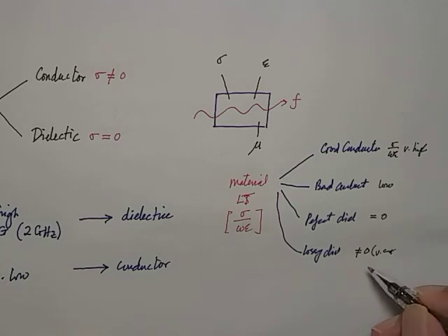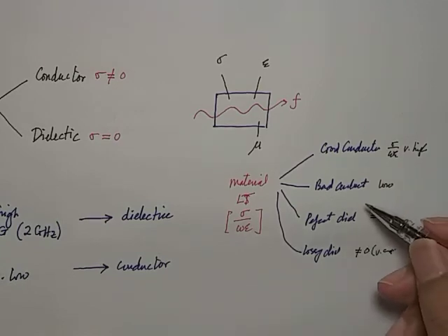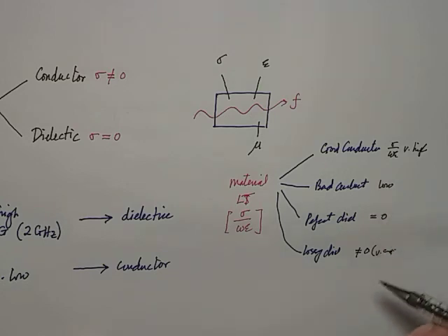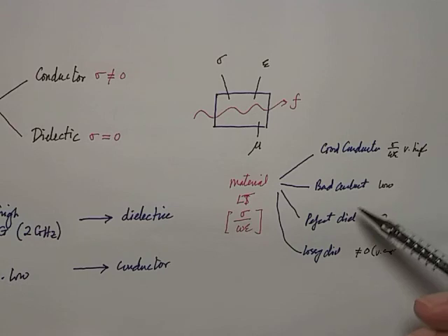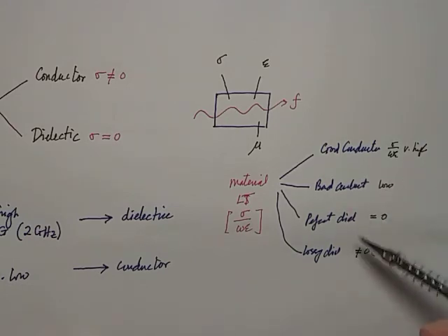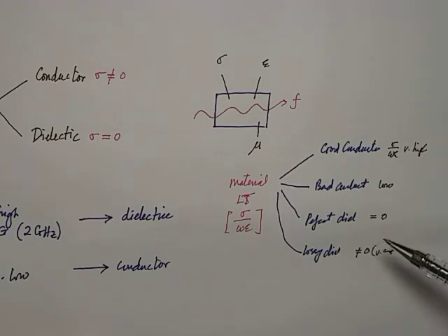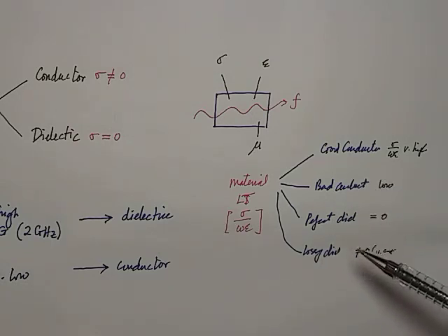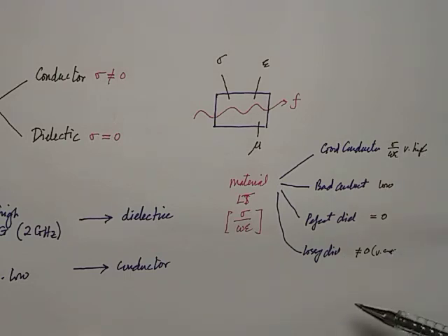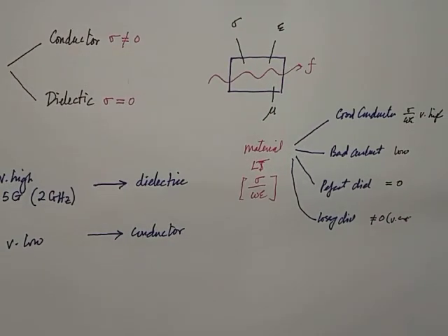So if the loss tangent becomes high, it becomes a bad dielectric, a good conductor. So you have to see that. The actual numerical value depends on the reference that you use, the standard that you use. Is it the IEEE standard? Is it other standards? Different countries try to propose their own standards, because by controlling the standard, they are dominating the engineering environment in the real world. So that's what you have to see. That should be a very important parameter, the loss tangent.